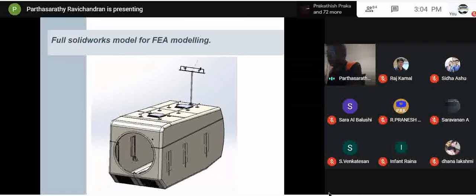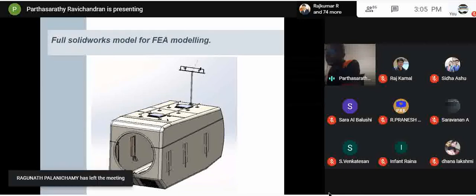So this is how the total assembly is. What you see in the top, these handrails, they also play an important role. Each of these handrail locations where the bolts are also there are also called anchor points. They have to hold 22 kilonewtons of force or load at each location. So that's what the minimum criteria is. I'm not telling you an arbitrary value. This is all given in the certification point of view, where they're designed, tested, and made sure that everyone is following the norm.